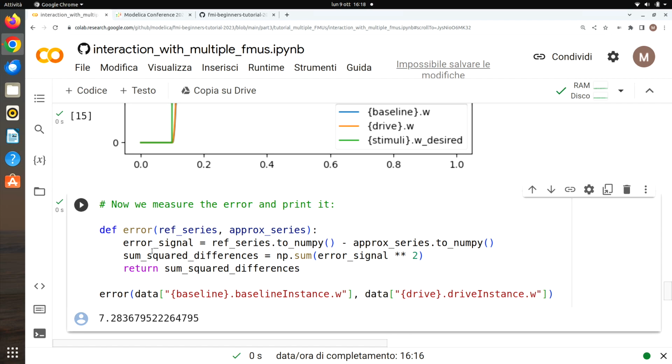Can we know a priori, before we run the simulations, how much mistake or error we are going to make at some instant in time? Before running the co-simulation, it is possible if you know the accuracy of the internal solvers and you know the order of the extrapolation being used in the inputs.